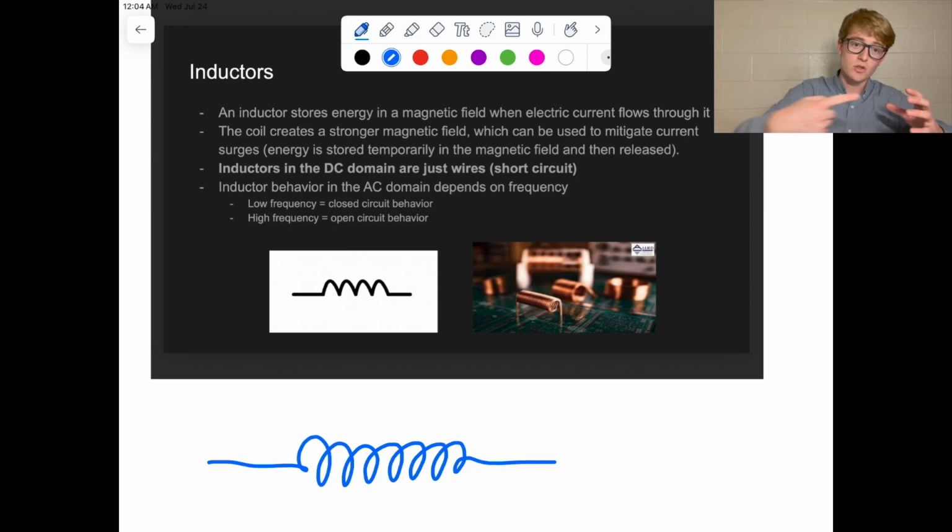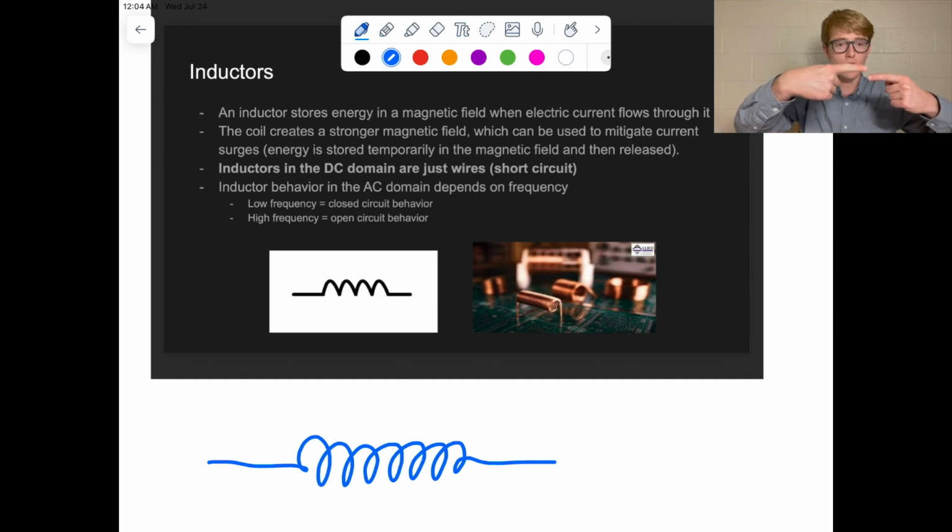And what that's going to do is cause current flow. So now I have a current input, and then the B field grows, and I have potential differences. That's going to have a corresponding current that flows in the opposite direction and cancels out my input current. So that's how an inductor is physically able to resist changes in current. So hopefully that explanation makes at least some sense. I hope I explained that as well as I could.